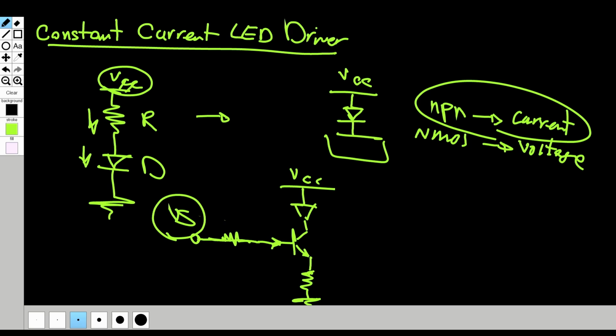So this VS could be obviously any voltage really, because the base of these transistors, like I said, do have some ratings, but they're not a voltage driven device, so they don't really care what that specific voltage is, as long as there's enough current that flows through the base.